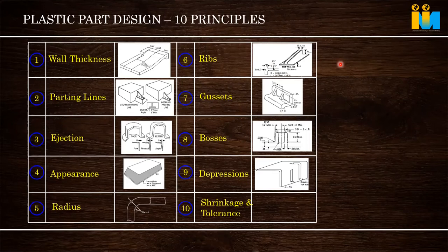See, I told you, polycarbonate 1.7 mm thickness. If we go to a copolymer, you can fill in 1 mm. That's how cost saving is being done. Raw material cost will increase, but here the weight will reduce. Some raw material will fit inside at the same cost. Then your transportation cost will reduce, logistics and packing cost will reduce, and the end product cost will reduce because of lower weight. So this is how value engineering is being done.